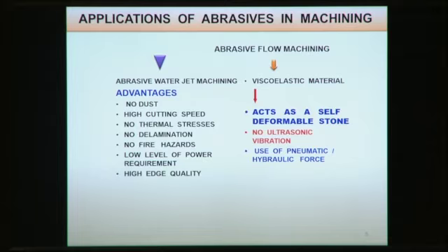There are no thermal stresses when abrasive particles hit the workpiece surface, so heat generation is very less. Unlike in conventional machining processes, here the tool does not touch the workpiece surface, so heat generation is less. Also, whatever heat is generated is taken away by the abrasive water jet.